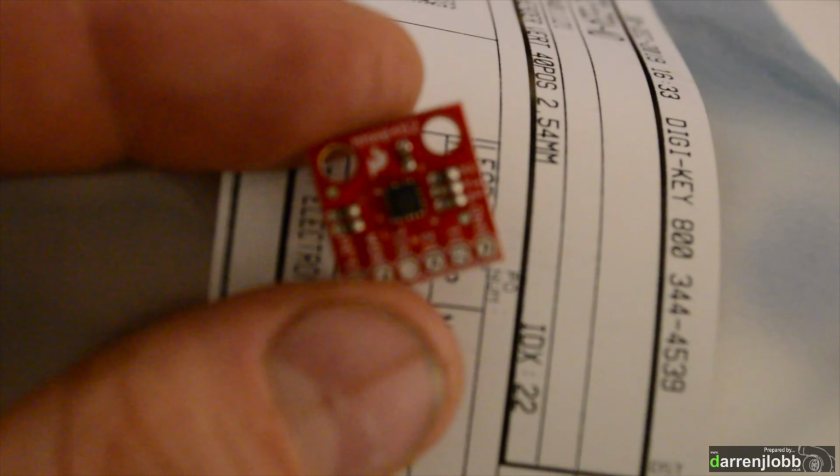So we've got our little MMA8452 chip here, again off eBay. The last little thing we've got to do is just solder on the pins or the headers and get that mounted on the board. One thing I did notice is if you just buy what's known as an MMA8452 chip, you may not necessarily find the specific one that you need to slot onto this board. This one here that's on a red board is made by SparkFun, I think. So you need to make sure you do end up with one like that, because you can also get variants of it which use a different pinout and some more pins, which obviously won't fit on the board. You can still technically use it if you mount it externally, but if you want the one that will drop straight in the board, you want this one.